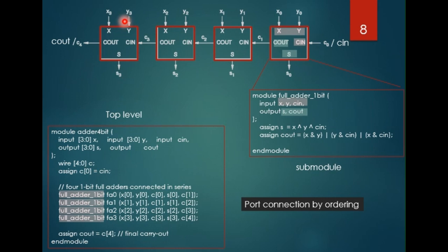Apart from the input ports and output ports, we also need to declare the wires. The internal wires consist of C1, C2, C3. But to make the description of the 4-bit adder in an iterative or array form, we can also declare the wire using a vector with the bits starting from bit 0. In this illustration, C0 is actually the carry-in of the LSB adder.